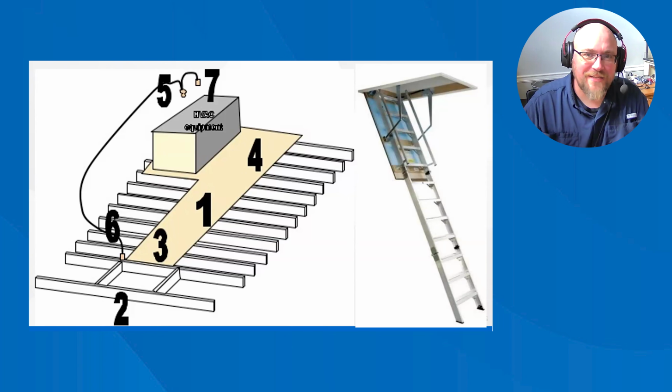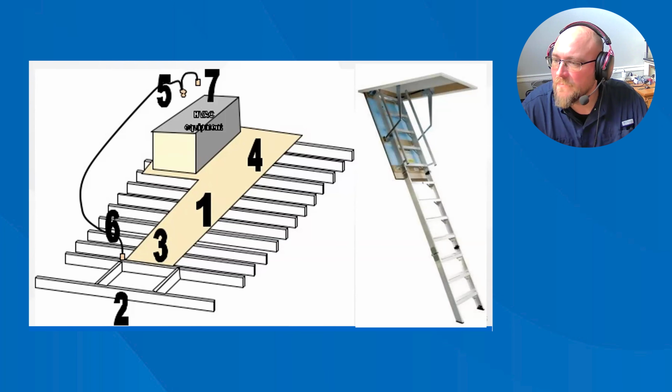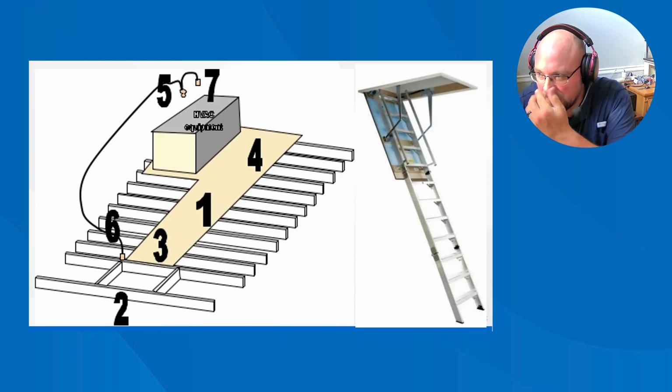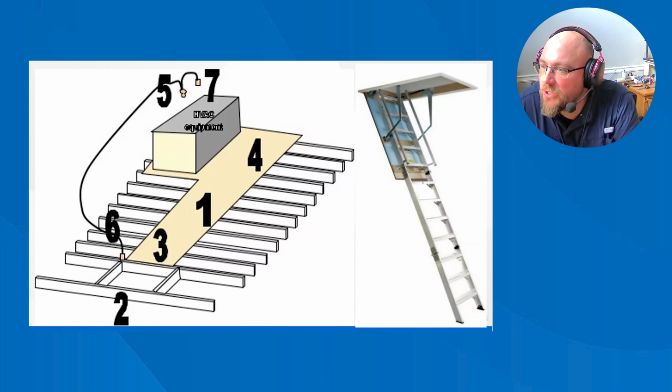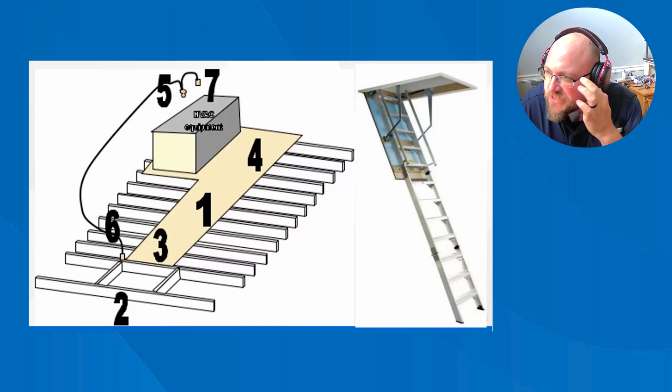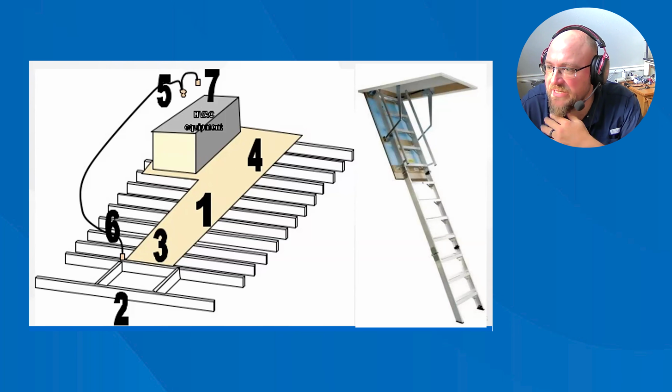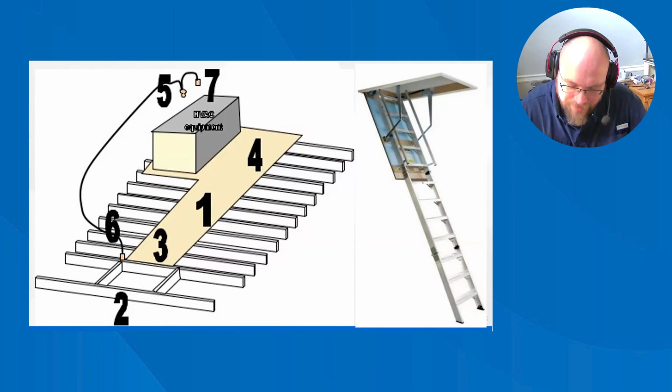If it is fire rated, there should be a sticker when you pull down the stairs. A lot of times it says that it is a fire rated attic pull down stair material. So, let's see. The closed ladder is covered with debris such as blown insulation or roofing material that's shed during roof work. Inspectors can place a sheet on the floor beneath the ladder to catch whatever debris may fall onto the floor. I would highly recommend that.